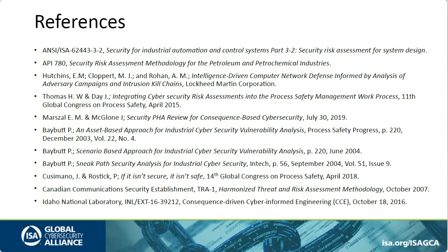And the reason for that is that when I worked in industry for an end user, all the operations folks would say, we don't have that information yet. We'll get to it. And then you end up doing the risk assessment after the plant is, let's say, 3/4 of the way through detailed design. And if that's when you do it, changes are very, very expensive.